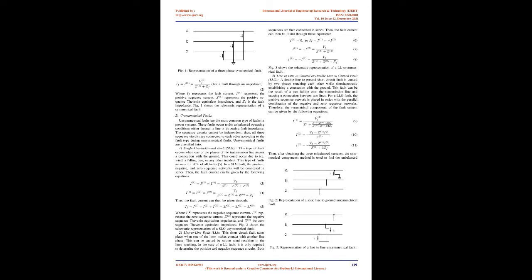Furthermore, all short-circuit faults are analyzed through the Thevenin equivalent sequence circuits seen from the fault point in power systems. Consequently, during symmetrical faults, the sequence circuits are kept independent. However, during unsymmetrical faults, the sequence circuits connect to each other at the fault point and cannot be considered independent. Finally, by utilizing the sequence networks and the symmetrical components concept, the short-circuit fault current is computed.